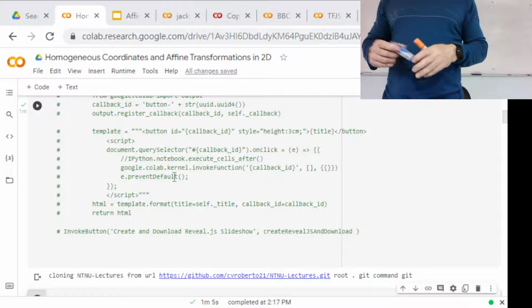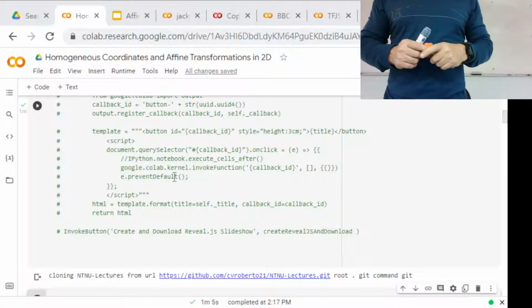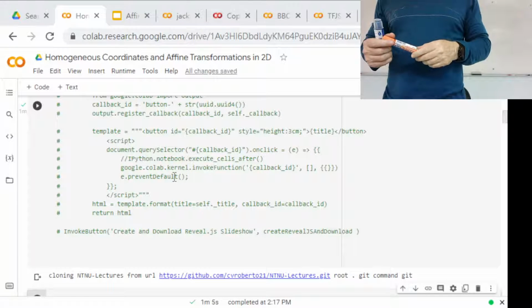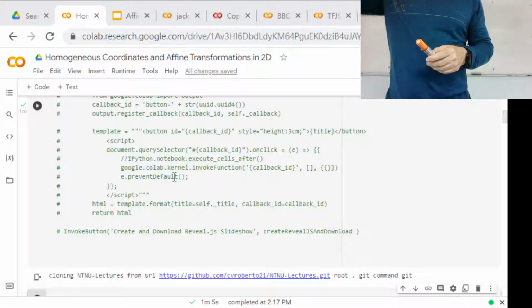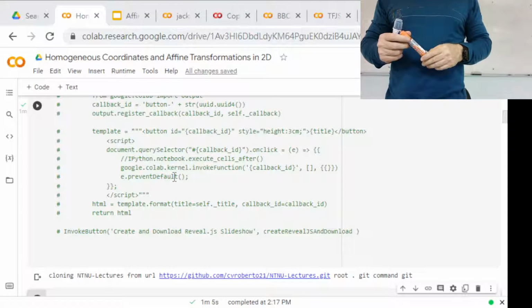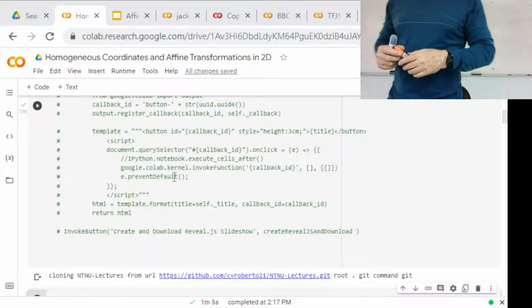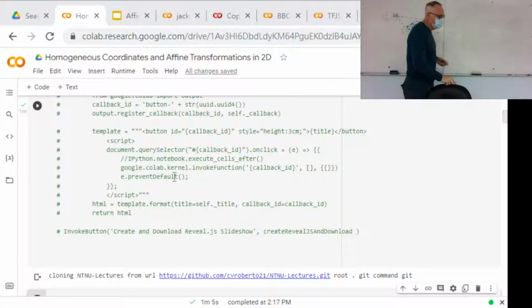But what we use mostly is that we assume that the ball is on the ground floor. Because right now, the robots, when they play soccer, they always kick the ball, but the ball very rarely actually goes into the air. Most of the time it's rolling on the ground. And because of that, I know one of the coordinates, so then I can figure out what that distance is, what the 3D point is. And that's a problem that we're mostly interested in when we're dealing with robot vision.